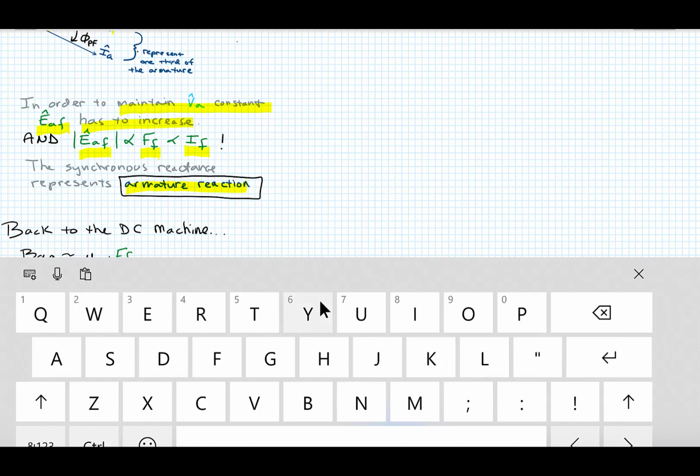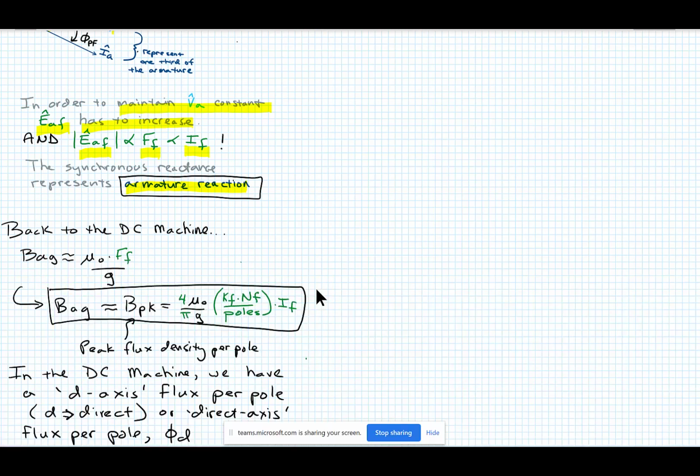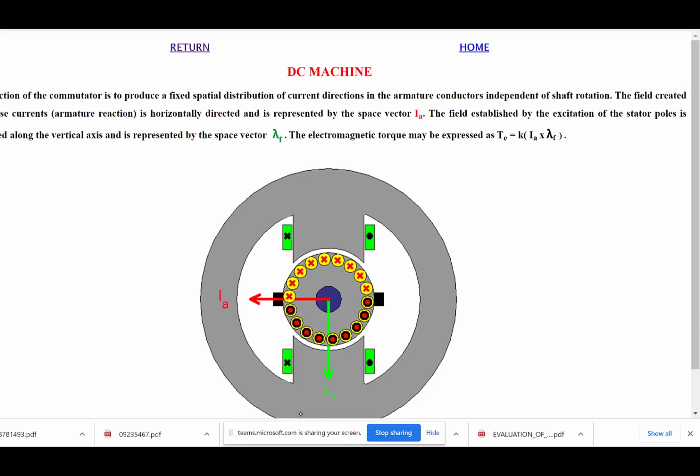So does one brush need to be positively excited and the other one negatively excited in order to cause rotation? Yeah, you can think of it that way. I don't like to think of it as positive and negative. I'd like to think of it as a supply and a return. It's like any circuit, right? You got your supply line current going in, and then it's coming out. So you have to have 2 because otherwise you broke the circuit. So you need to have 2 brushes, one to supply it and then one to bring it back.